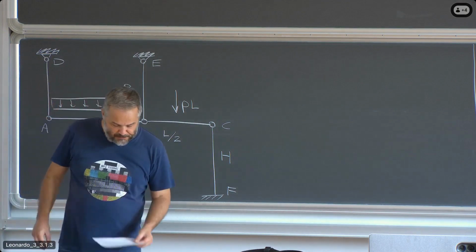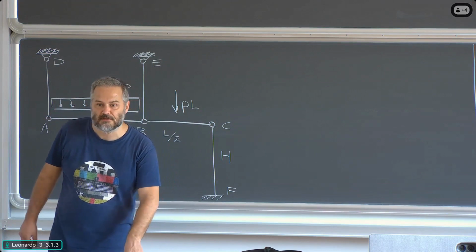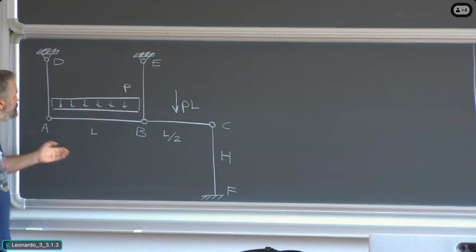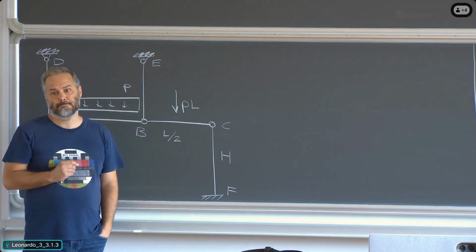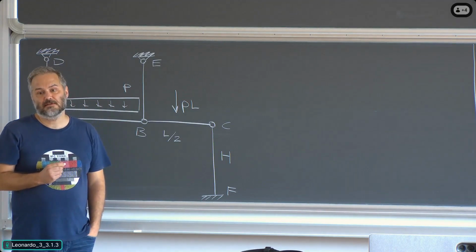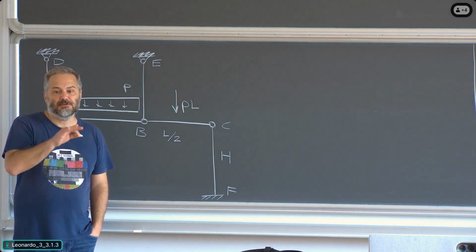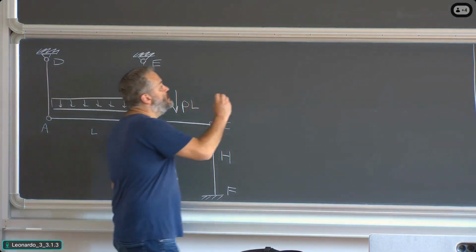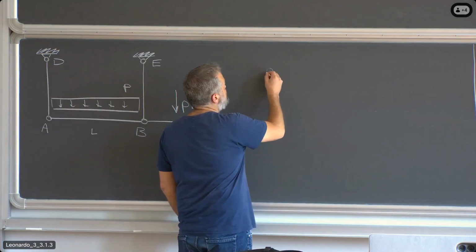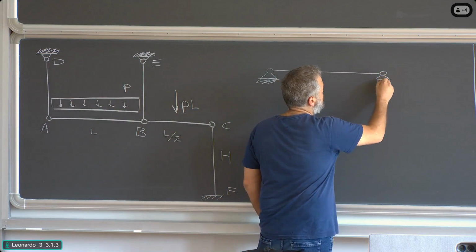First point, as I said previously, asks you to perform the structural analysis of the 2 beams. Okay? So let's look at the beams. How do these beams look like? They have hinges at the ends, okay? Which means they are no different in terms of shear force and bending moment from a simply supported beam. So both AB and BC could be studied as regards shear force and bending moment as if they were simply supported.